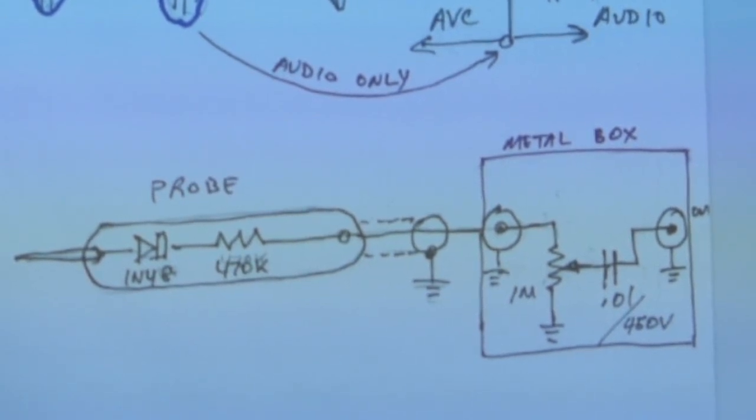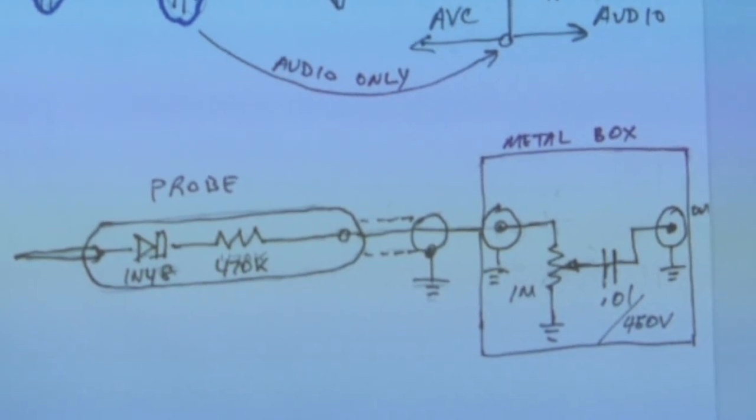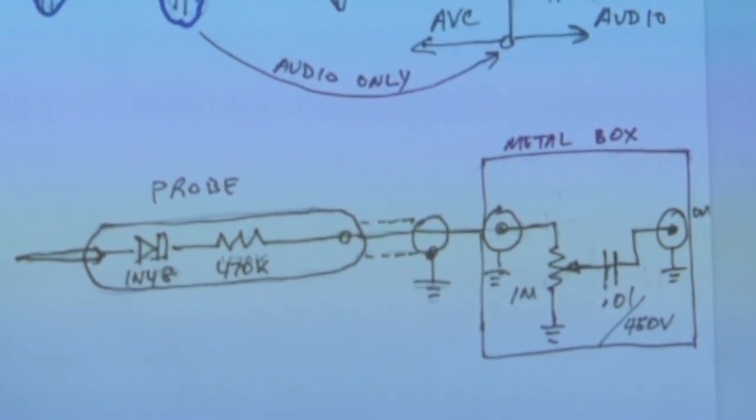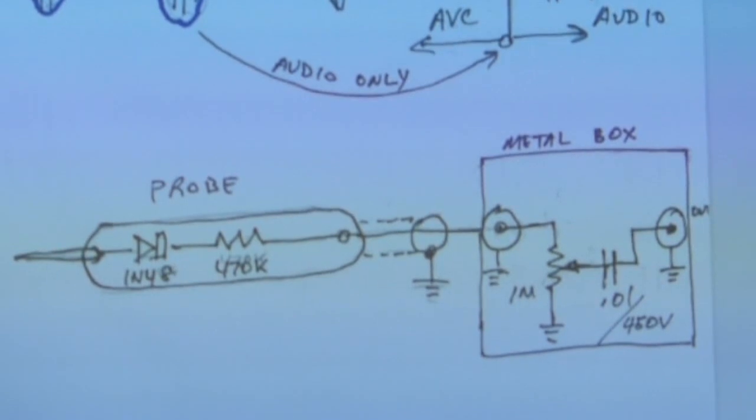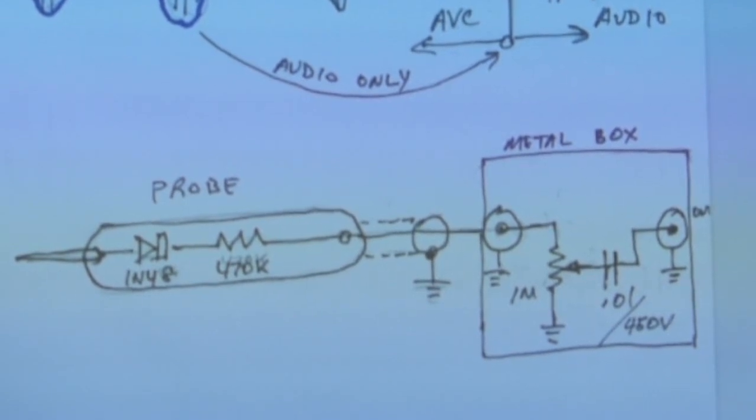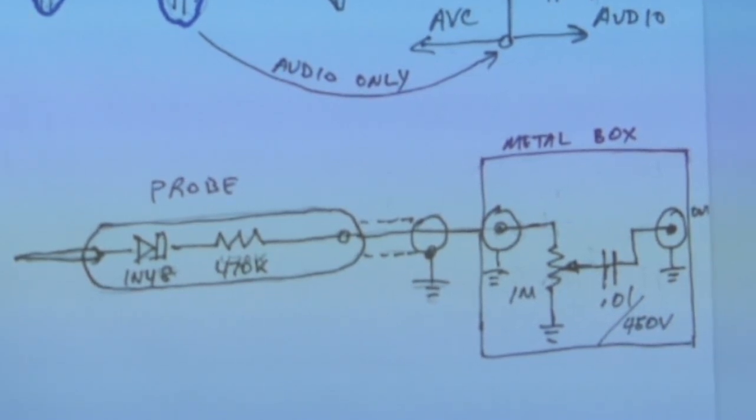Now, the reason I say CD or tuner input is because those are high gain audio inputs. And all you need is an RF detector in the front of them, and you can make those work as a very effective signal tracer. I hope you know what I'm referring to, the component radio tuners that are around now. Things have moved on from that day, and you can get them for a good price. David has a number of them, so cheap but of good quality.